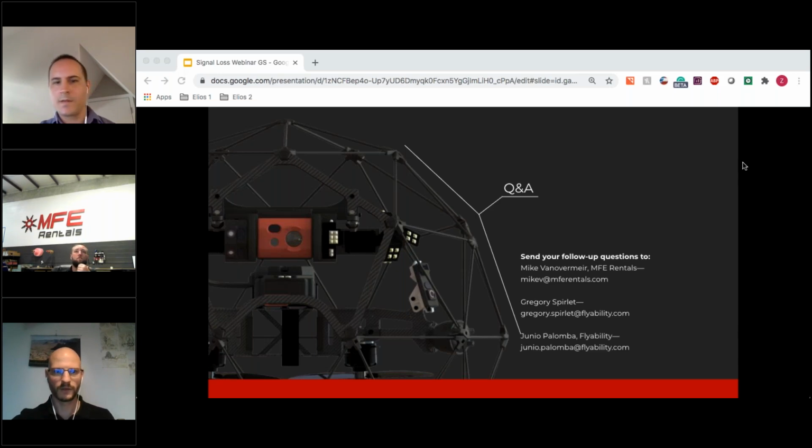Okay. Right. So as far as I know, the signal uses several bands, so it hops between frequencies. If it notices, for example, another drone or another equipment using one side of the spectrum, it'll move to where it sees less interference. But by default, the signal for controlling the drone is an uplink, and the signal coming back from the drone is the downlink, which contains the video. So as far as I know, these are separated signals anyways, because they're moving in different directions.